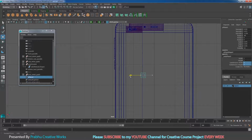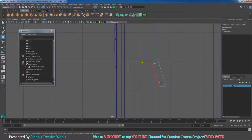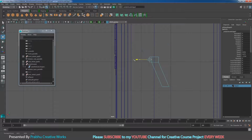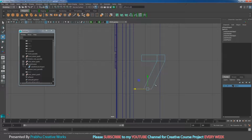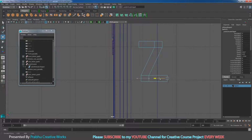So press W like this. So I will give my logo a Z shape. I didn't mention any company name. So I will select this edge, move it to this side, shift right click and choose extrude and move a little bit up. Then I will select this edge, shift right click and choose extrude edge and press W over here. Then select this edge, shift right click and choose extrude edge and press W. You want to move in Y, so select this edge, extrude edge, press W and move over like this. So right click and choose object mode.